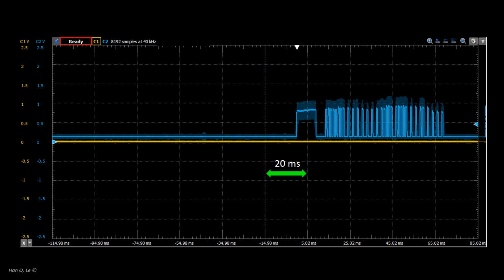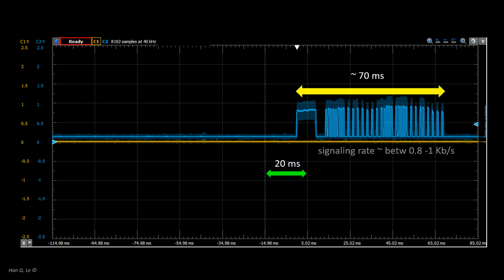The following are a few more notes about the remote control. The data here are only for one remote. There are a couple standards for infrared data communications and your remote may have different properties, nevertheless, these are the features you can look for in your measurements. First, try to obtain a whole message associated with a command, such as, turn up the volume. This example shows a burst of signals over a duration of approximately 70 milliseconds.